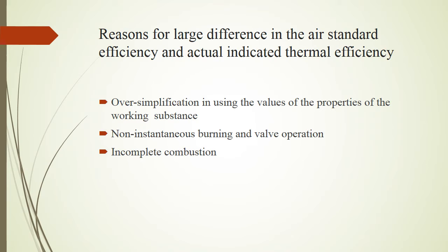In the case of an actual engine we do not have instantaneous combustion. We do not have instantaneous valve operation, be it closing or opening of the valves. But in the air standard cycle, what did we assume? We assumed that the combustion process, that is the burning process, is instantaneous, taking no time, 0 degree of crank angle.